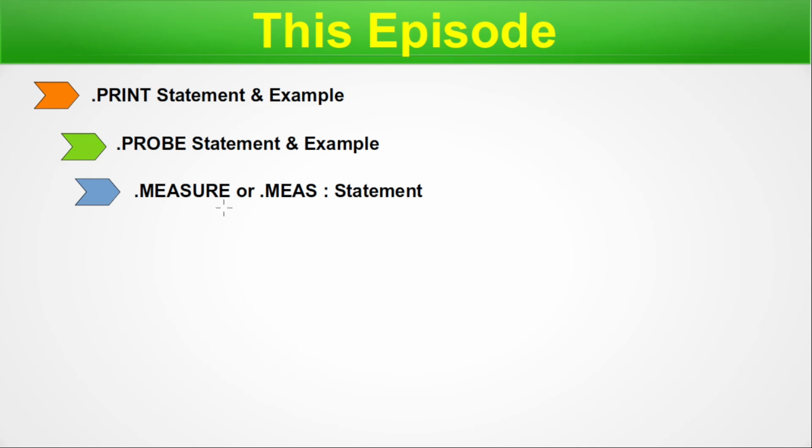Next, we will talk about the dot measure statement. We will go in detail, and this is the smaller shorthand of dot measure, which is usually written in the SPICE deck to save some characters and for quick and easy writing of the command. Next, we will talk about the significance of dot measure command in VLSI, where in the different areas of VLSI, the measure has an impact.